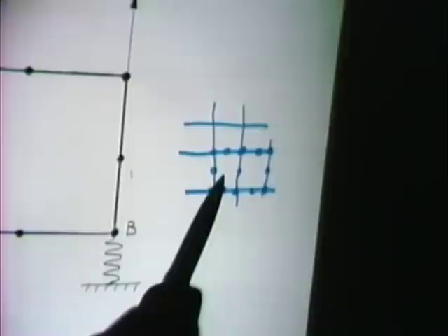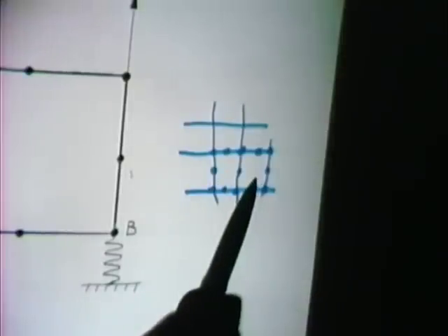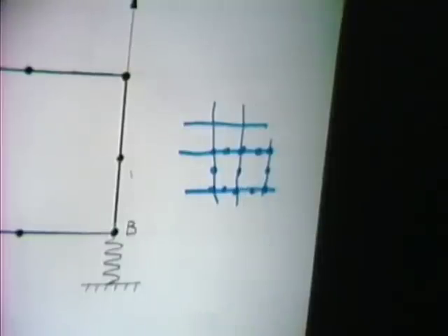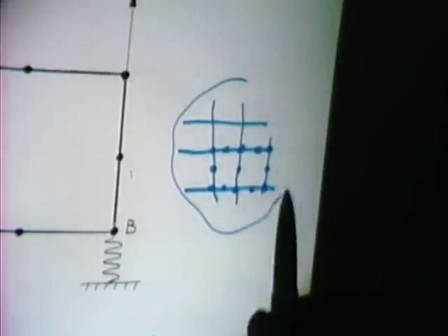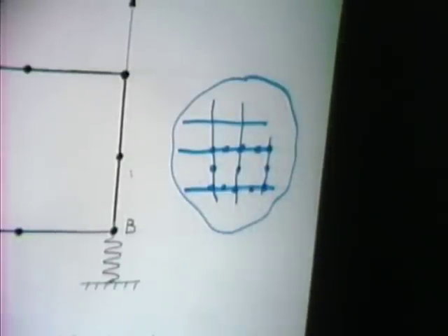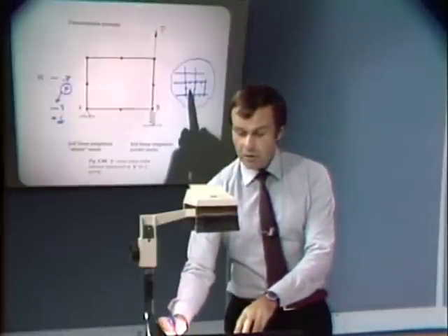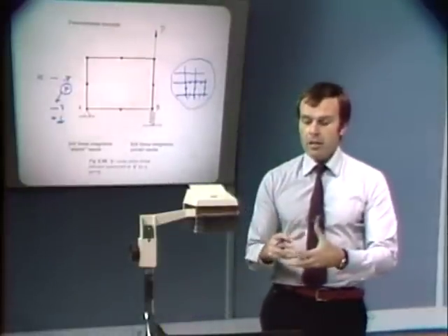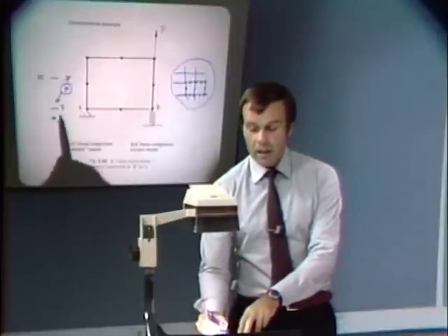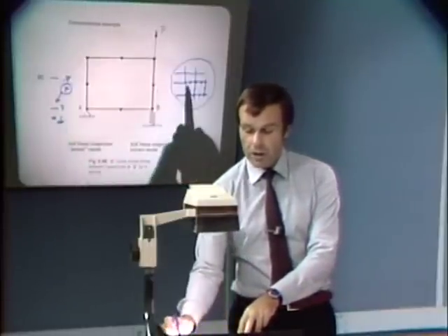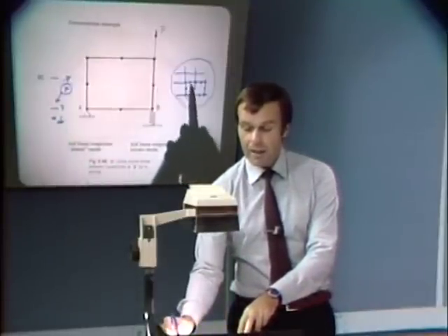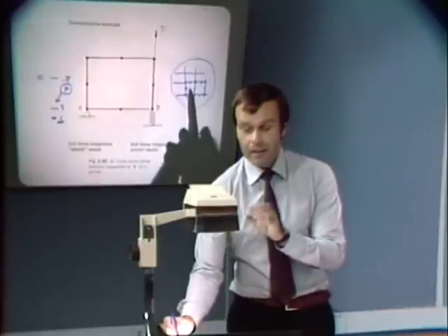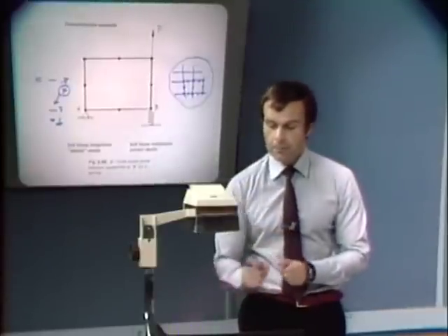And if we use 2x2 integration for this element and 2x2 integration for that element, we might very well be able to solve the equations very nicely, and we might in fact get good results in an analysis of a more complicated problem, because the stiffness of this element and that element each compensate for the rigid body mode that still is available in this one element here.